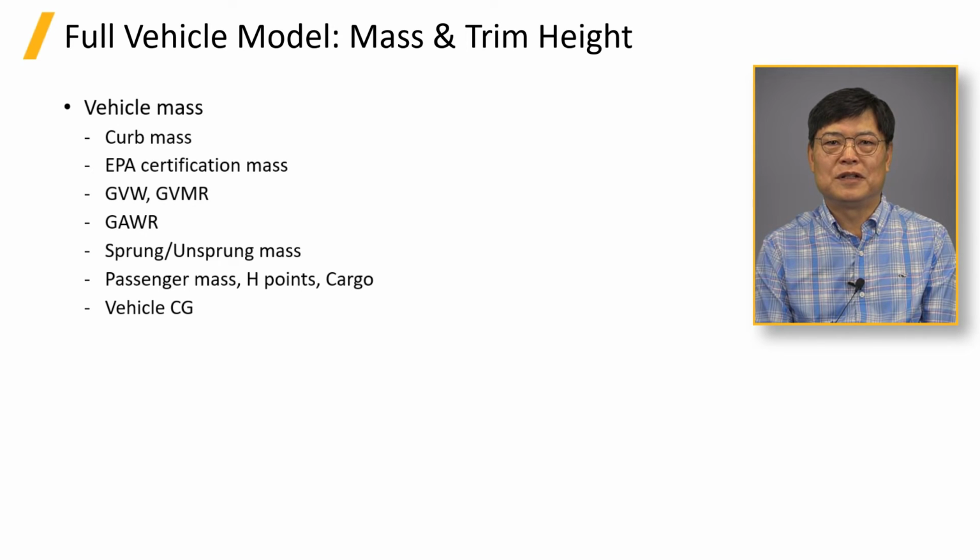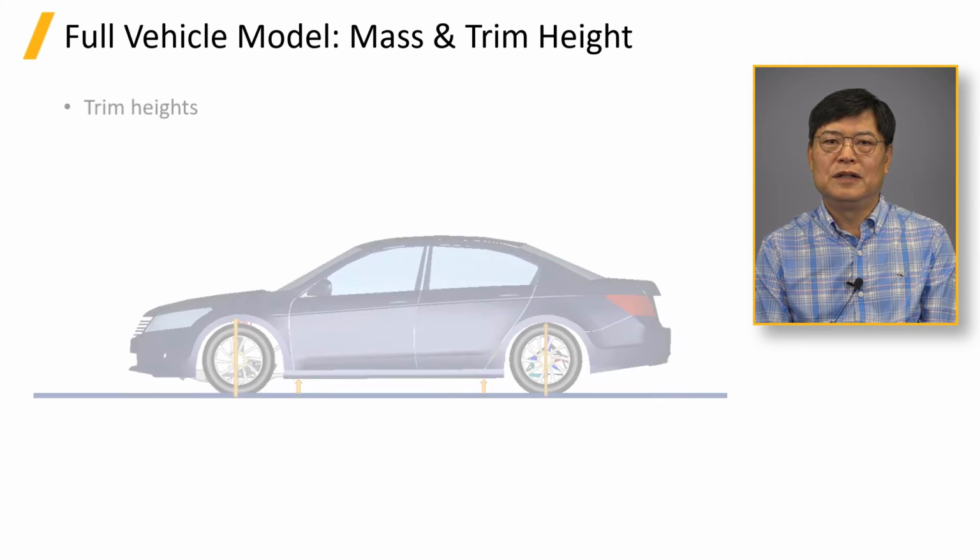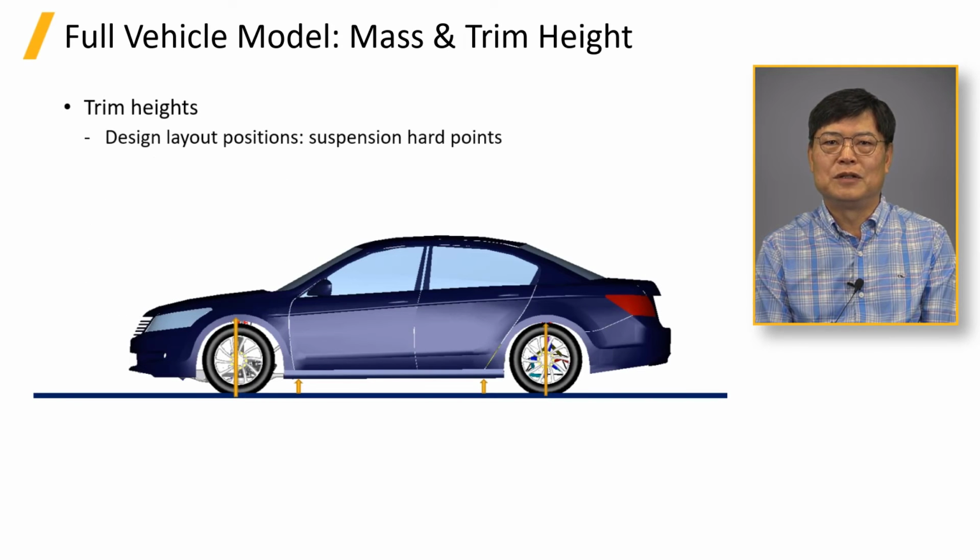Suspension hardpoints are defined at the curb ballast. Since hardpoints from the CAD files have no preloads, there would be slight discrepancies between a CAD and a multi-body model loaded at curb. Adding more ballast means the vehicle height changes, the vehicle sitting lower. The vehicle trim height is a distance measured from the ground to the point in the vehicle.